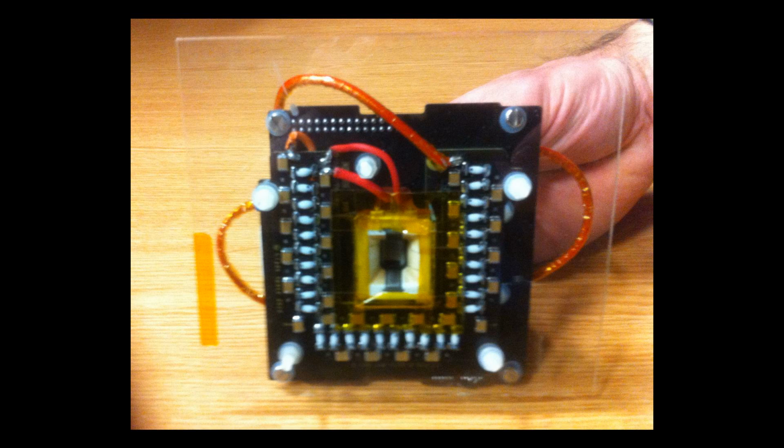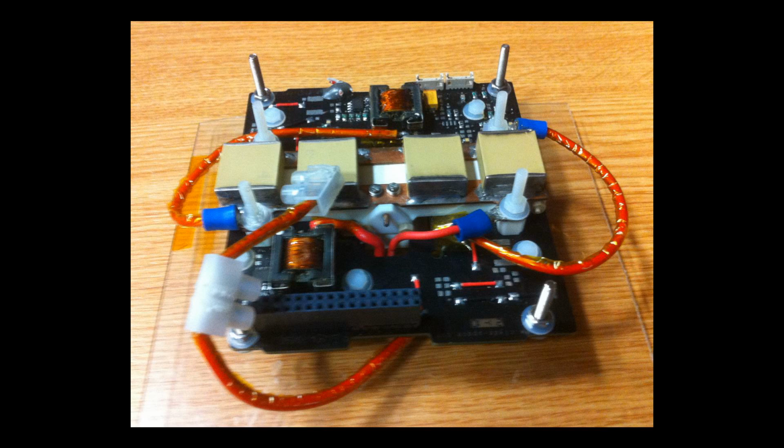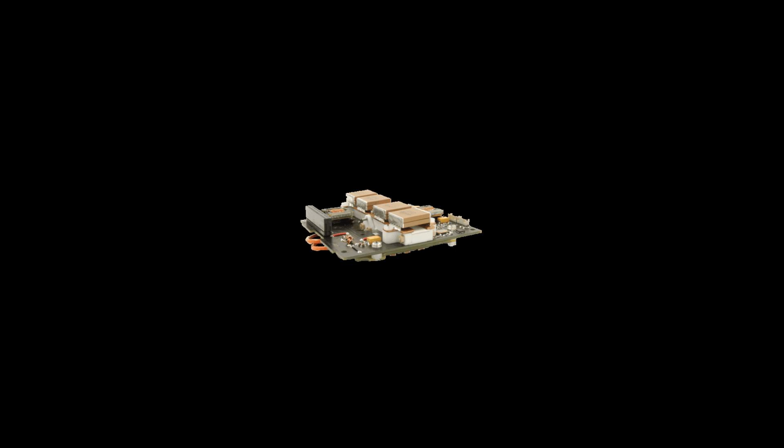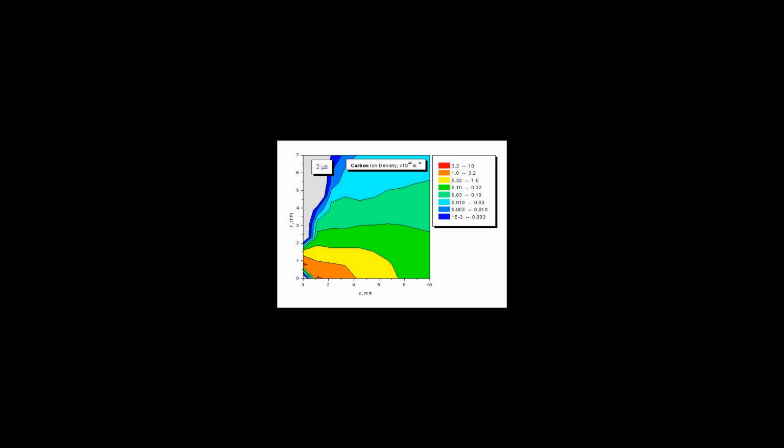Due to the force of the ablation, the plasma is propelled at low speed between two charged plates, an anode and cathode. Since the plasma is charged, the fuel effectively completes the circuit between the two plates, allowing a current to flow through the plasma. This flow of electrons generates a strong electromagnetic field which then exerts a Lorentz force on the plasma, accelerating the plasma out of the PPT exhaust at high velocity. Its mode of operation is similar to a railgun.